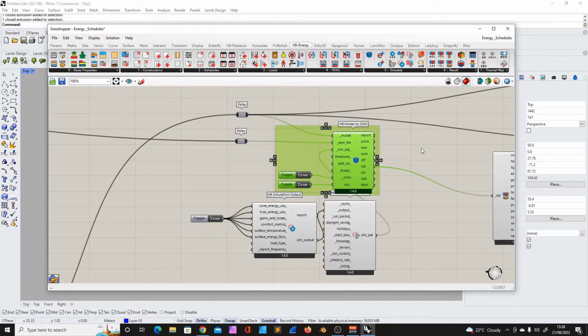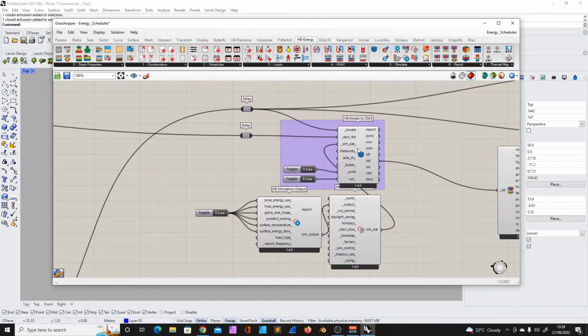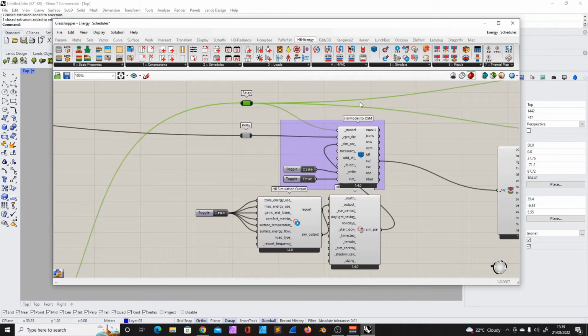We've done that in one of the first videos, so if you haven't seen it, maybe you go back and have a look. I will not go into that because this is all about Grasshopper and what we could look at inside Rhino from that model. But yeah, you can even tweak stuff inside the OpenStudio app. So whatever you feed in here as the model, with the weather data and whatever you need, like the simulation parameters, where here we just decided, for example, what we want to test and what we want to have within our simulation, all this is fed into the OpenStudio model, which you then can open in the OpenStudio app, and you can find it written in your output folder.